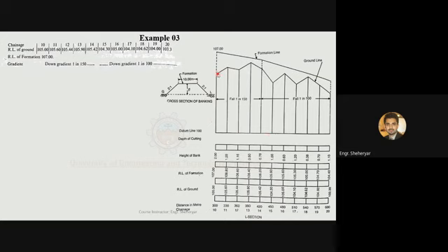Now you are actually measuring the road reduced level, road height from any reference level. So at this distance, the road was having height of this much. Then you move towards the 30 meter point horizontally. The road height increased till this point. Then you moved ahead and road height decreased a little bit. Not the road height, I'm talking about actually the ground profile. The road is not constructed yet, so it is uneven. So you can see that the ground is uneven.